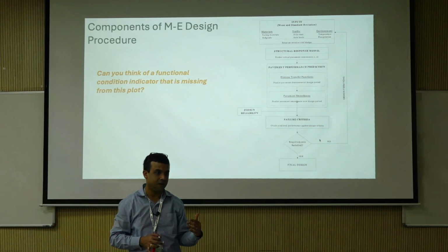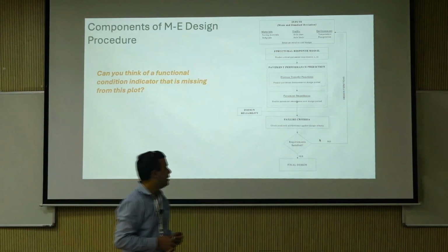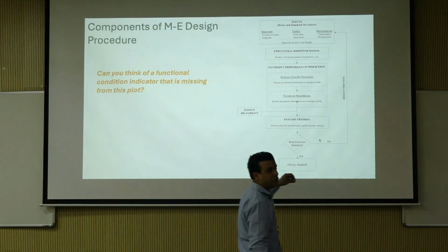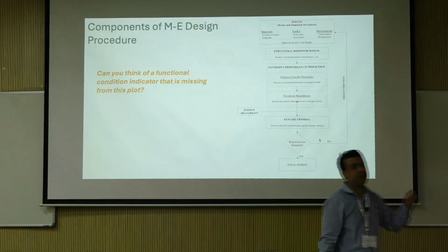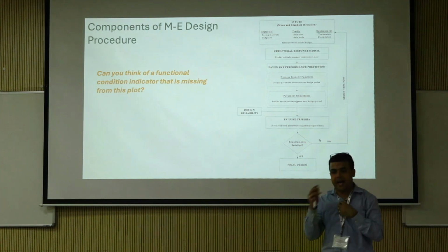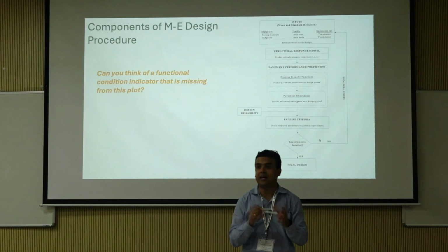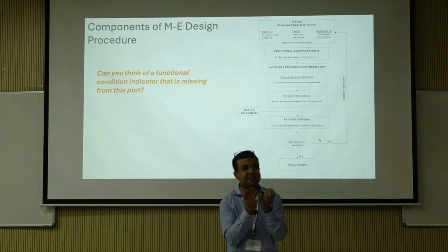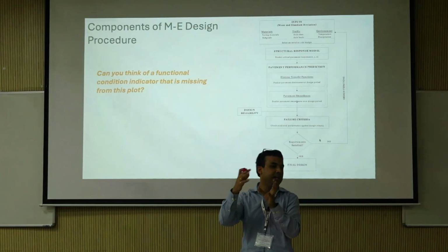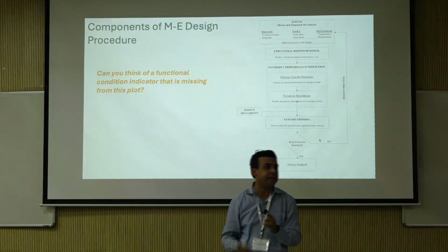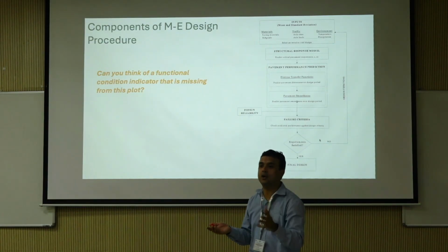So you as an engineer will have to decide for what material, what property, what level you have. The unfortunate part is that in the current version of the mechanistic empirical pavement design guide, for aggregates and soils, level 1 input does not exist, because stress dependency of resilient modulus is not directly considered. It is just assuming a constant modulus value.